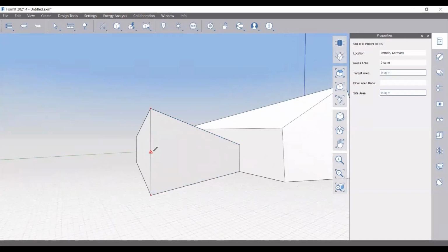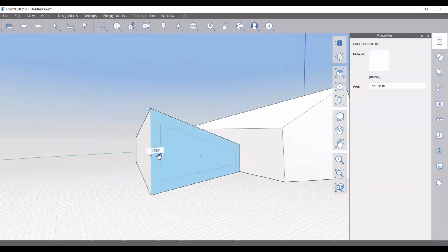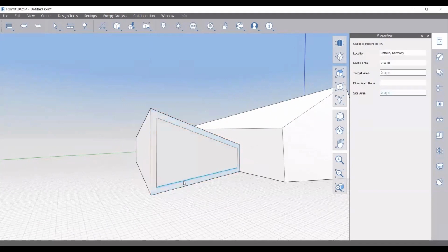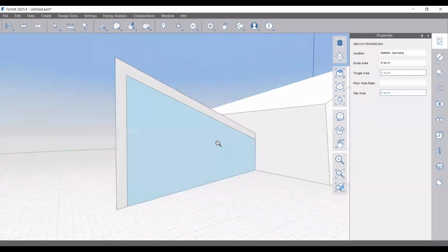Now I wanted to make some elegant surface on my facade, right. So what I can do over here is make an offset plane at a distance of 0.3 meter, right. After doing this you have some unused lines, so I'll just connect those through my surface.